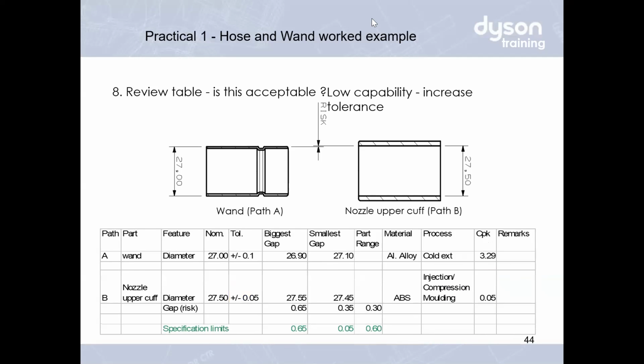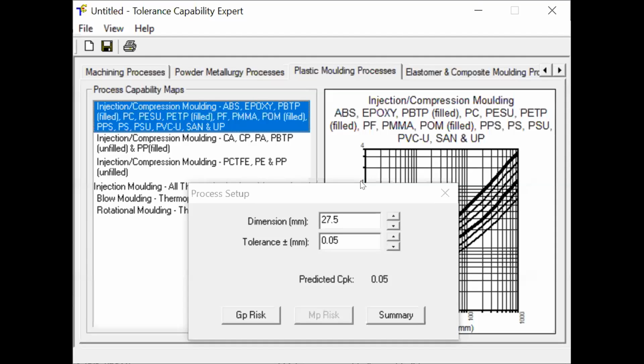So what should I do to make sure that I'm able to do that? I have to use the same software again. I'm not going to change the parameter, I'm going to change the tolerance. For example, if I change the tolerance to 0.1, the CPK only increases to 1.55. How about I change to 0.20? Oh, it's 4. I can keep on trying, 0.18, 3.98. So at the end, I know that I should design the tolerance to 0.2.